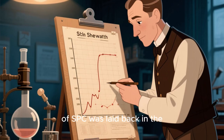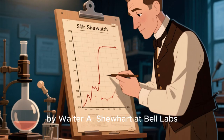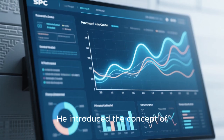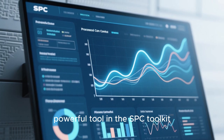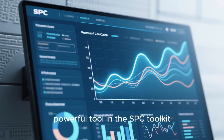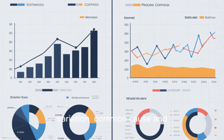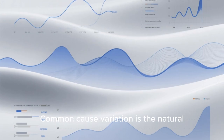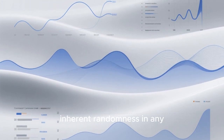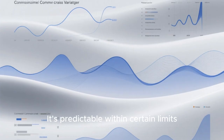The foundation of SPC was laid back in the 1920s by Walter A. Shewhart at Bell Labs. He introduced the concept of control charts, which are still the most powerful tool in the SPC toolkit. Shewhart identified two types of process variation: common cause and special cause. Common cause variation is the natural, inherent randomness in any process, the background noise. It's predictable within certain limits.